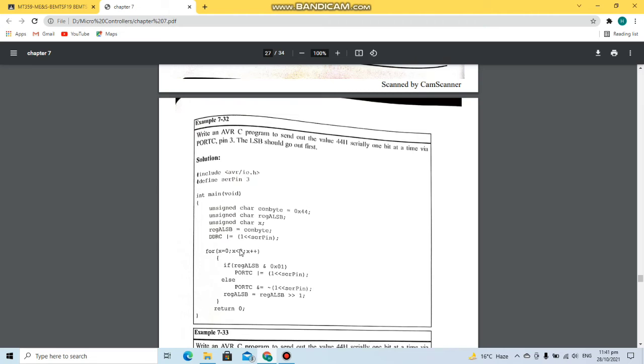When we are performing the AND operation, we know that when AND is performed with 1, the bit is unchanged, and with 0 it becomes 0. So with 0x01, only the first bit will remain unchanged, and the others will be changed to 0, as anything ANDed with 1 will have no change, and anything ANDed with 0 will become 0.